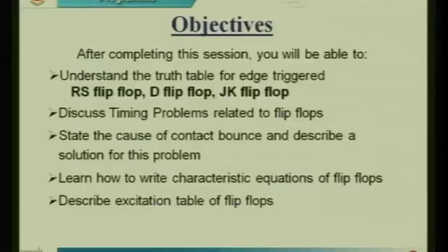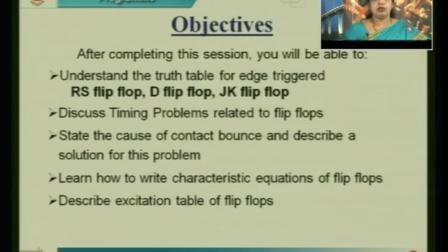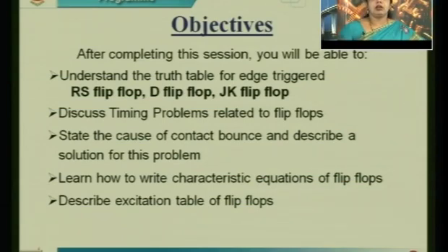In view of that, we'll discuss in depth the edge triggered flip-flops. It could be RS, D and JK. We'll discuss how the JK flip-flop works. We'll discuss the timing problem related to these flip-flops, and there is another concept called contact bounce.